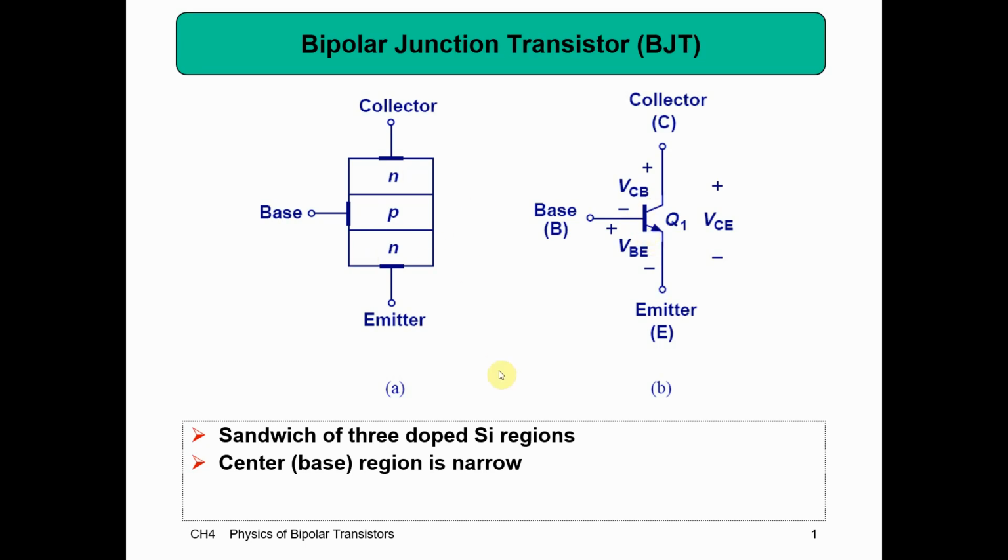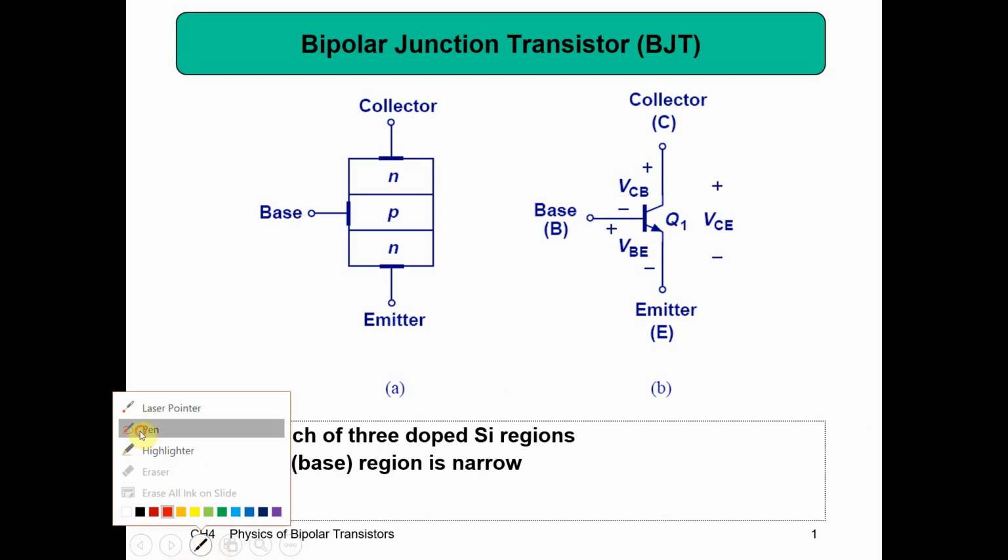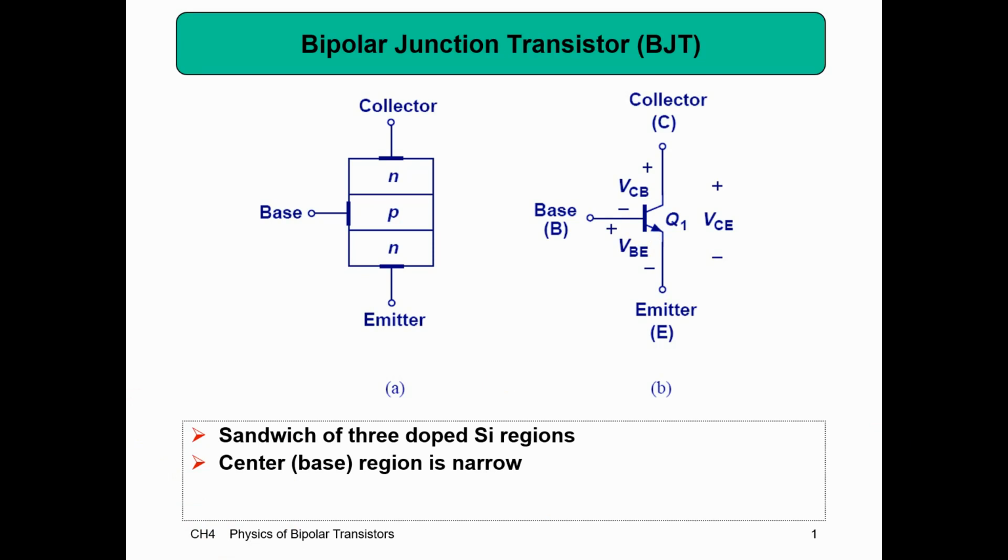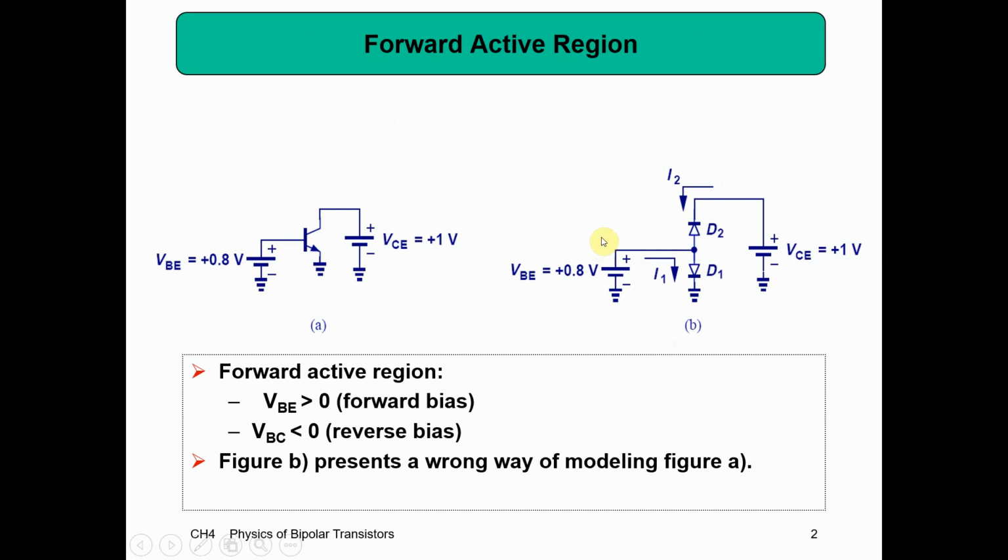So we look here at the NPN and we can see that a PN region that we had before was just a diode. Well, there's also a PN region on the top that looks like this. So it really just looks like two diodes with a connection in between the two diodes. Now that kind of looks like what we have over here if I have two diodes.